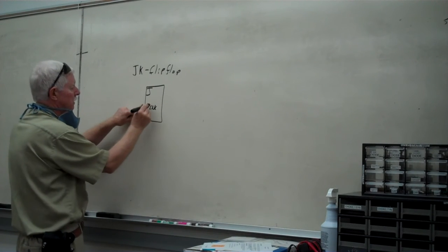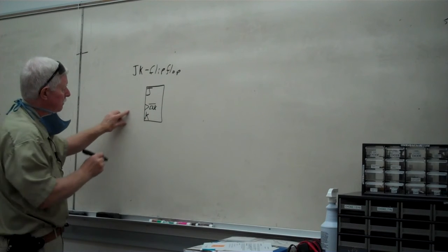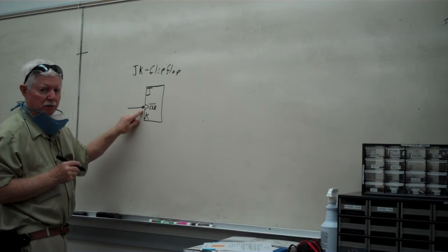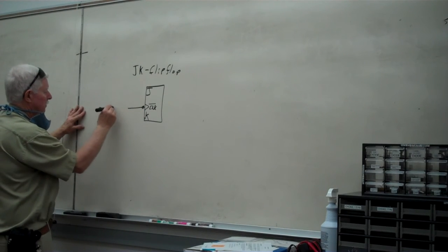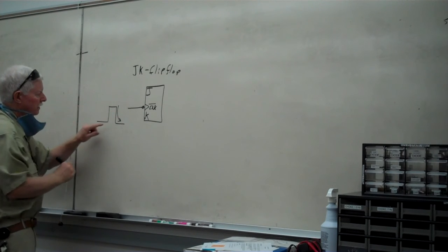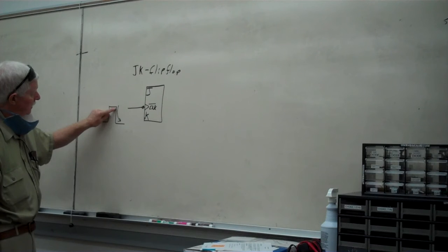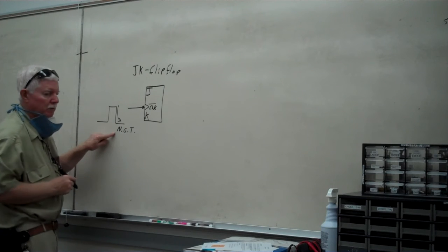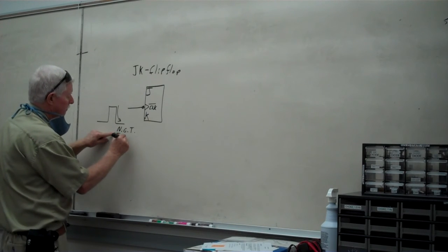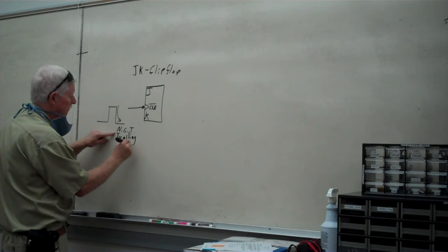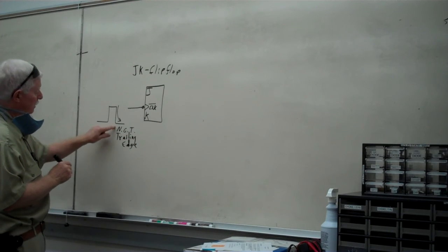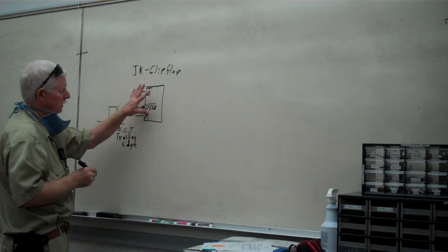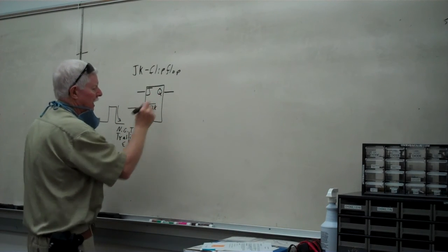And for this particular one, I'm going to use the complement bar above the clock input because a lot of these actually do have, see a little bubble down here, actually use this on the trailing edge of a clock pulse. So when it comes up and goes this way, this is when this particular device will activate. It's on a negative going transition, over the trailing edge of the clock pulse. Whatever is appearing on these, according to the truth table for this device, it will determine what this is going to have on its output.